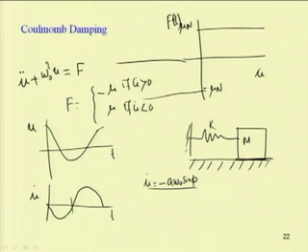So, we know this force F(t) can be written as mu n signum u dot. So, when u dot is positive, it will be plus mu n, and otherwise it is minus mu n, but as we are taking u dot equal to minus a omega 0 sin phi, now one can write this F equal to minus mu if u dot greater than 0 and equal to mu if u dot less than 0.